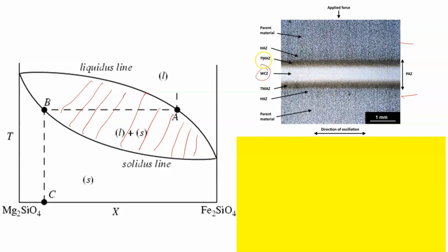What you'll also notice is that your heat affected zone is actually very, very tiny. The temperature didn't go nearly as high. Most of it was focused in this area where it was recrystallized. Anything else was still in the solid state. There may have been some temperature migration up here, but it's a very, very minimal heat affected zone in solid state.